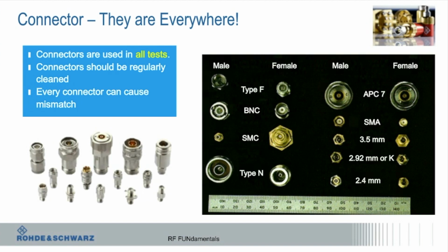3.5 is a precision connector, so it has an air dielectric. It doesn't have the white stuff there. It's an air dielectric with very precisely machined tolerances. Guess what? They cost more. Your manager probably doesn't like that. They'd say, buy the SMA. I like the cheaper ones, but it's got to work. If you look at the specs, there's a spec for a 3.5 millimeter connector in terms of frequency range, VSWR, and all that. I think it goes up to 26.5 GHz, just off the top of my head. With SMA, you'll see stuff where they say 18 gig. It depends. It's not a standard.